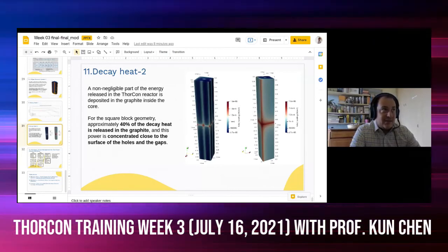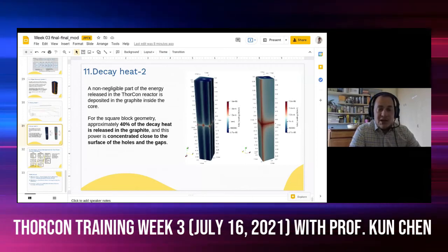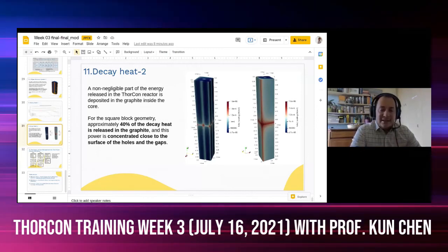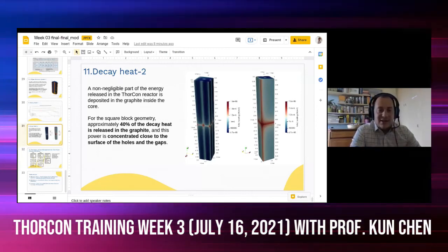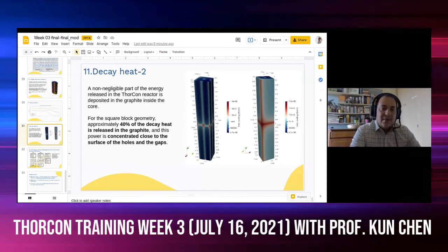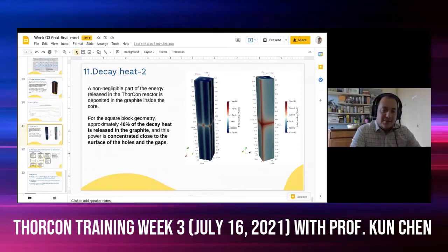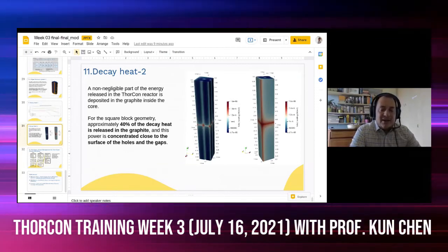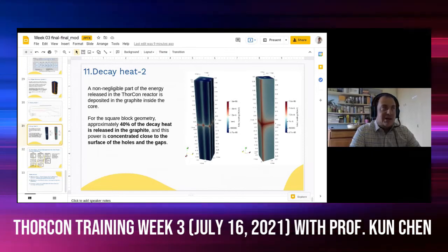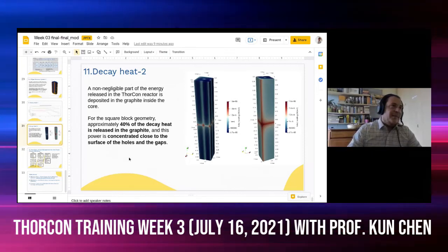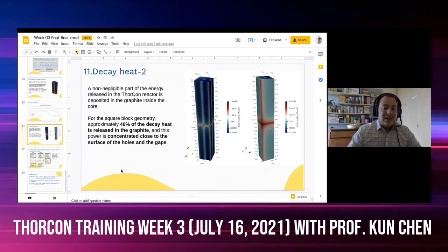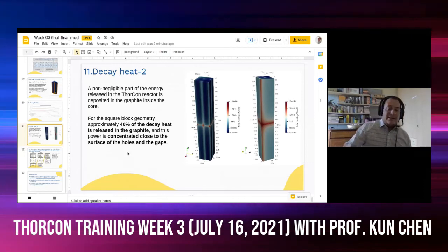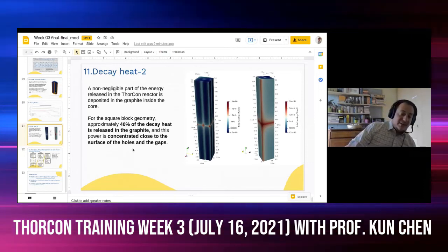And this is for a twofold reason. One is just the heat transfer between the salt that is heating up and the graphite that was initially at a higher temperature with respect to the salt, but soon after is surpassed by the salt, which sees a larger decay heat, and the fact that some of the decay heat goes straight into the graphite. This proves very effective in reducing the maximum peak temperature reached by the drain tanks after an accident.